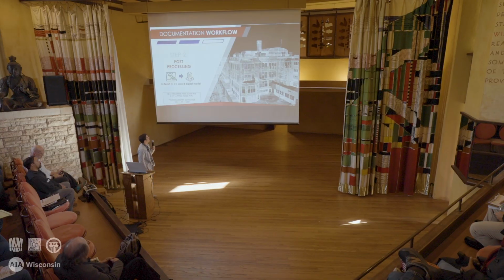And so we have listed here some file types that we kind of see as an archival standard. So E57s have been around as long as point clouds have been around. And so for the most part, if a software can handle point clouds, it can import an E57. So it's always nice to get to that and export your registered point cloud in that file format so that it can live on a hard drive and it can live as an archival source.